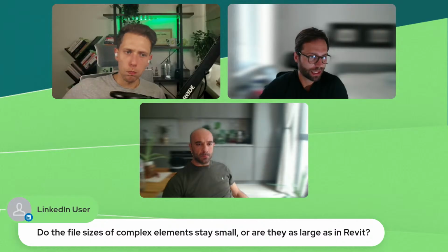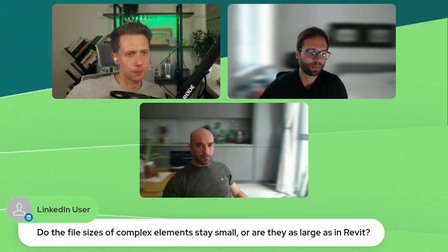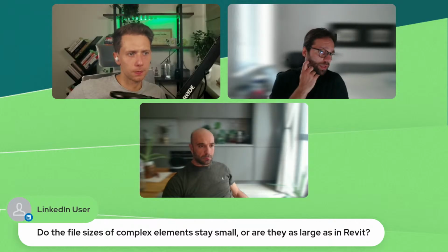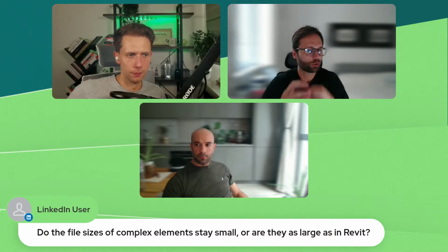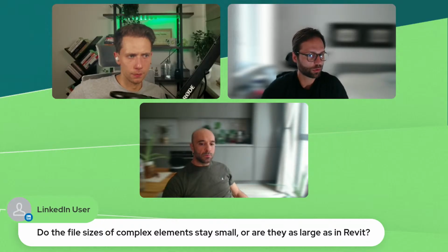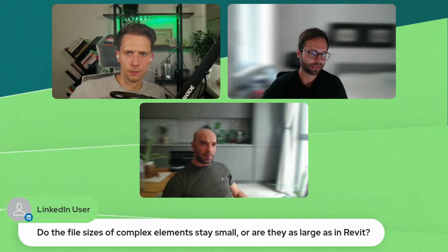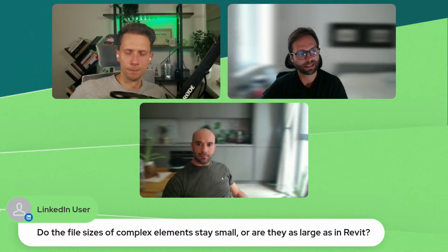By reducing the point count on the surfaces, even on a polysurface, and also the point count on curves, that will reduce the file size and the size of the geometry, because all the coordinates of those points have to be stored and also processed. When you press F10 in Rhino, it's a good way to see all the control points of your surfaces. So the less you have, the lighter the geometry is.